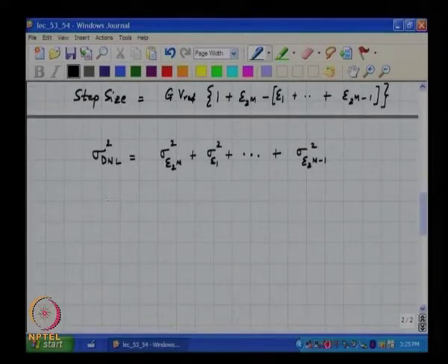Now, let us recall that sigma E2 square is what in terms of sigma E1 square? It is 2 times sigma E1 square, and please note that sigma E1 represents the standard deviation of the single current or the single conductance in this particular case, correct, and you make larger G's by simply taking these unit G's and putting them in parallel. If you want 2 G, you put 2 G's in parallel.